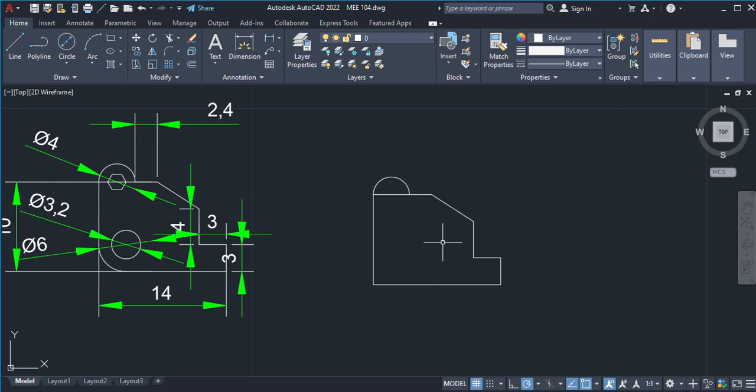So this side, the diameter is 6. If I'm not wrong, the radius will be 3. Like yesterday, you can do it in two ways. Either you use fillet, but fillet is the fastest way for exam purpose. You tap on this, tap on R.